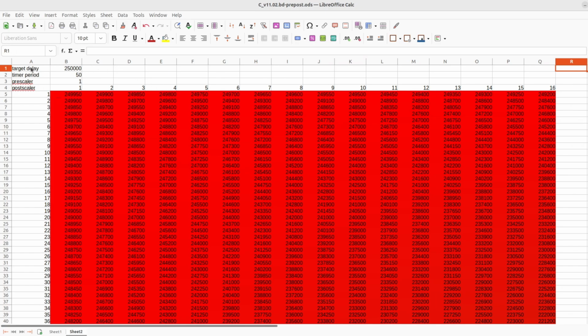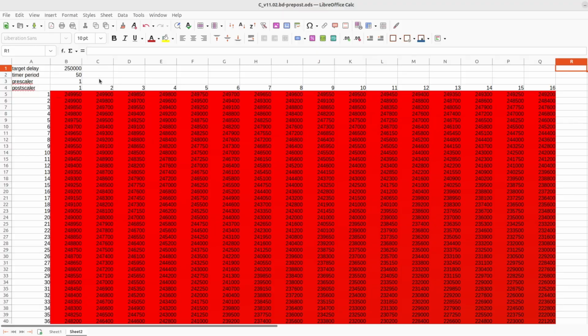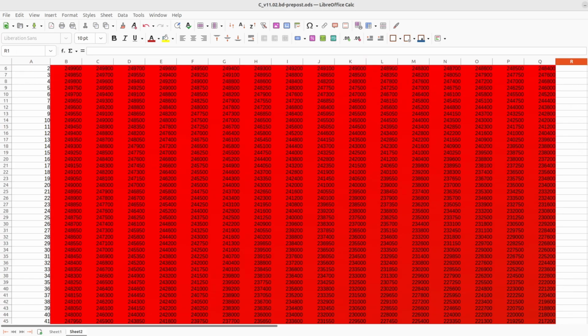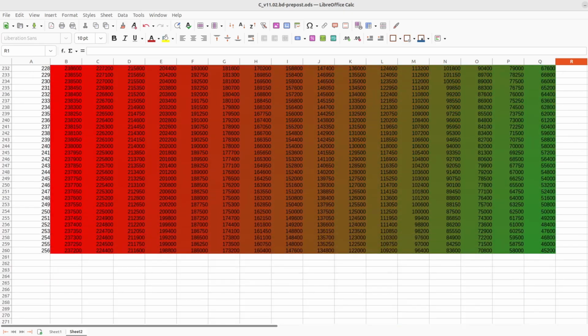And in order to figure that out, we just have to do the math. The idea is to start small and work your way up. So you could do it manually, or you can use a spreadsheet, like I've done here. I define a target delay of 250 milliseconds or 250,000 microseconds. We've already calculated our timer period at 50 microseconds. This is based on the 20 kilohertz input timer. And then I choose a prescaler. I'm going to start off with 1. And then I create a matrix of postscaler values, and in this case we go from 1 to 16, and the actual timer count along the y-axis. And in this case we go from 1 all the way to 256.